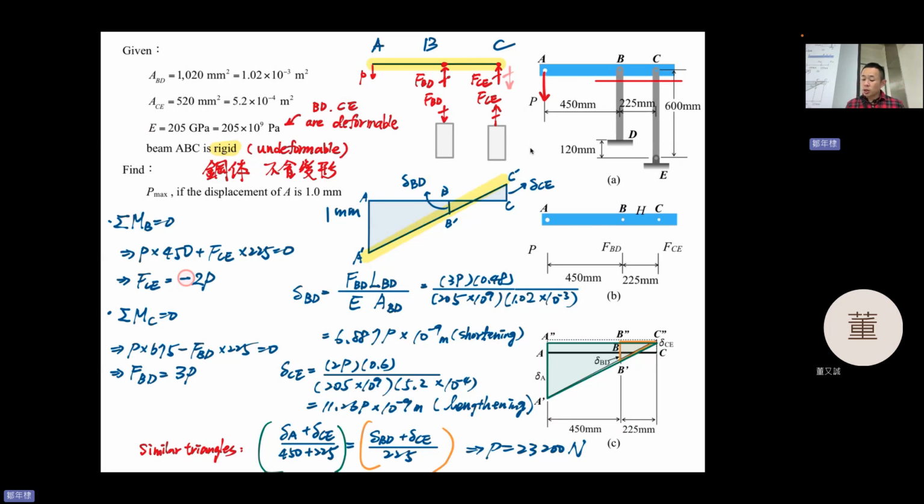Then you do the force equilibrium for the upper part, and after the moment balance you may find your assumption was wrong, and then you can change the direction. And a really important thing is that when you get the force on the upper part, you will also notice that the bottom part has the opposite force with the same value for its counterpart. So here it's downward, and this one will be upward.